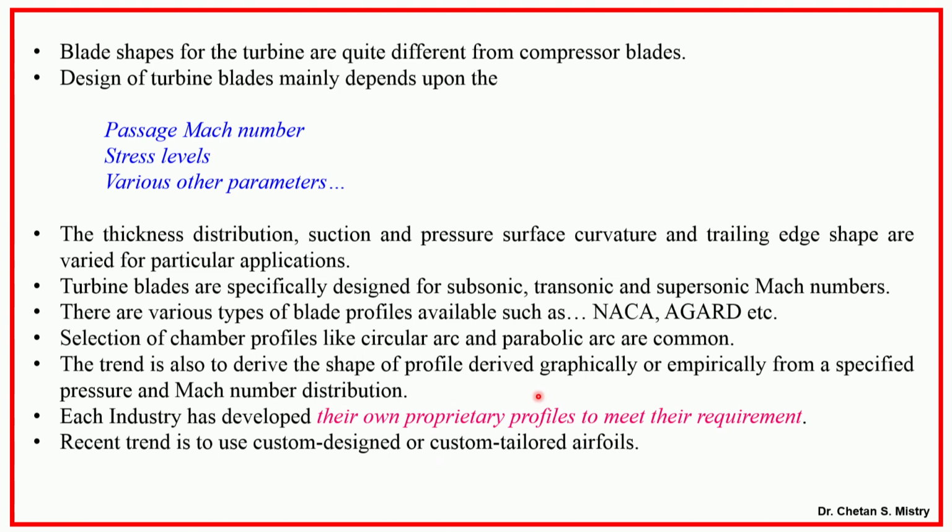That means you need to modify it based on your CFD study. You can do your numerical study, try to understand what is happening on my suction surface, what is happening on my pressure surface. Based on that physics understanding, you modify your profile. Maybe you need to change the thickness of your aerofoil, the maximum camber, the maximum thickness, the leading edge shape, or the trailing edge shape. Okay.